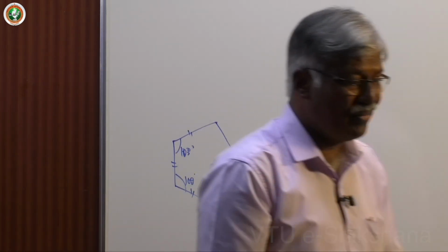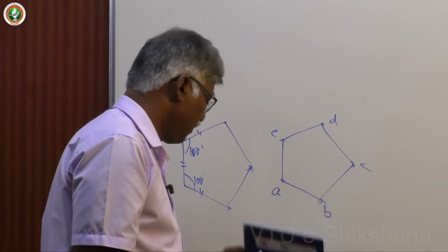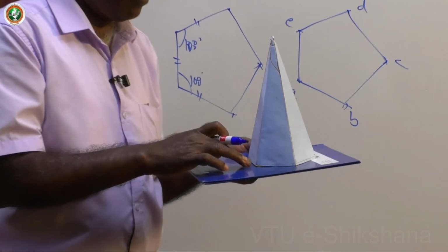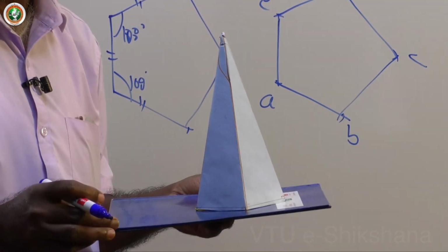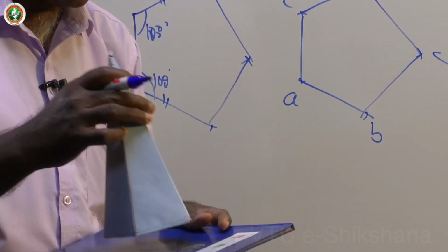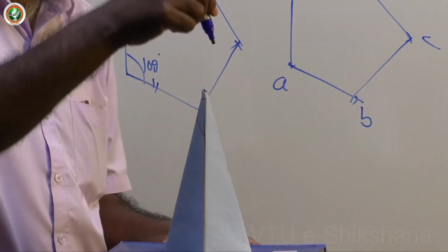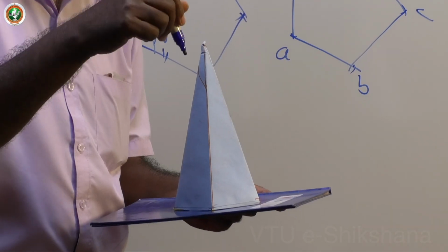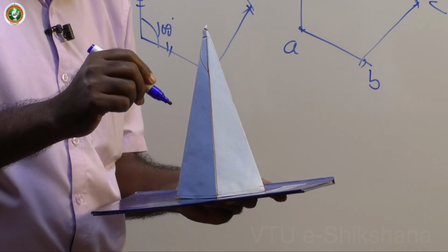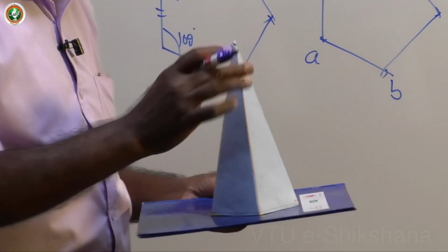Now if I take a pentagonal pyramid, you have the base edge perpendicular to VP. A simple position I am showing. These are the base edges and these are slant edges for a particular height. Now if you look from top, you will get the top view as a pentagon, even though the base is not visible, the boundary is visible, as the edges of the base and slant face edges are common. So that is why this is visible.